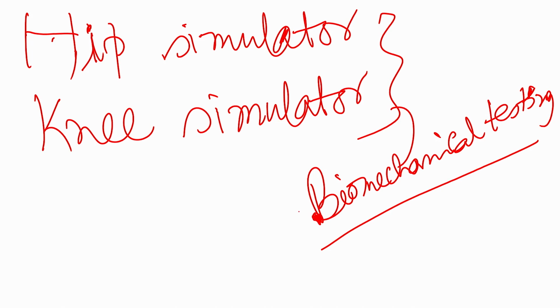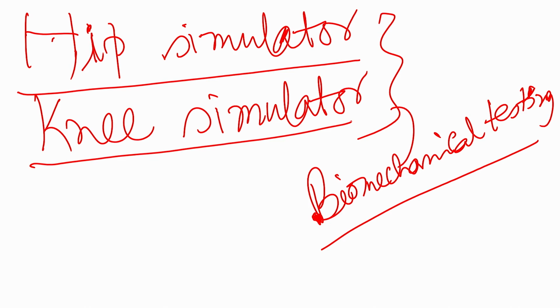What is recommended is that when you have manufactured a new femoral head, you test it against a clinically used acetabular socket. After the test is over, say after 1,000,000 cycles under the walking phase of the gait cycle, you can collect the debris particles and use them for toxicity studies. One can do the same for the knee simulator. After the knee simulator experiments are over, one can do similar toxicity studies for the implant materials.